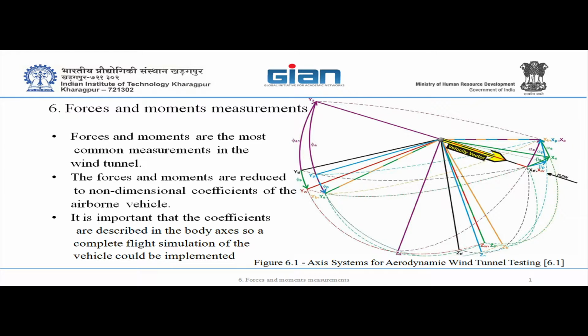You have the balance frame of reference, you have the wind frame of reference, you have the body frame of reference. At least 3 you have there. And you have to take care and know exactly what you're doing to transform from one system to another system. So this is the essence of this confusing thing.